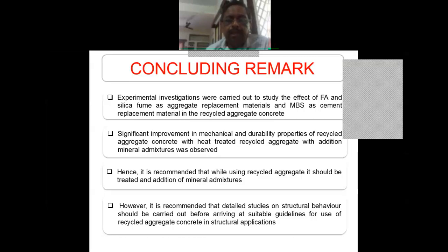Same way, for these recycled aggregates or any supplementary new aggregates, you should use them in the concrete with proper properties of aggregates. You cannot replace just as it is, and it has to be taken in volume adjustment and properties and other things you have to take care.